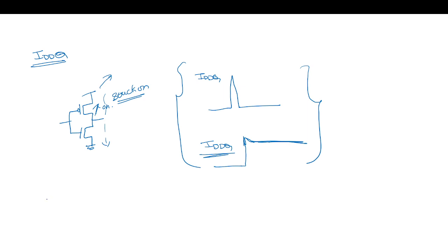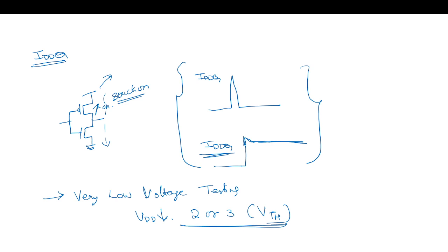And there are other testing methods, such as very low voltage testing, where we reduce this VDD voltage to 2 to 3 times the threshold voltage to detect certain faults. So this detects a few other faults. So these are fault testing methods.